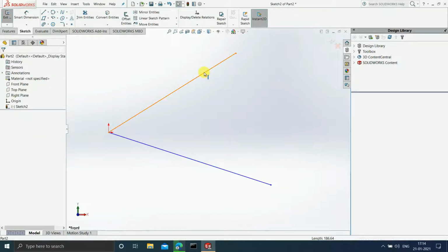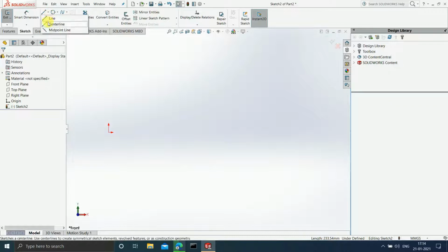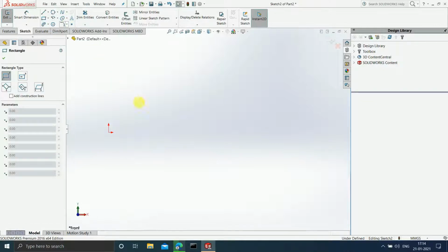Okay, so guys, now we have understood the circle command, and now we are going to move on to the parallelogram command. Okay, now if you drop this down, you can see that there are 5 options available. Okay, so let us understand all the options one by one. So if I select the corner rectangle command, in this what happens is that I can choose the opposite two corners. I can choose the placement of opposite two corners of the rectangle.